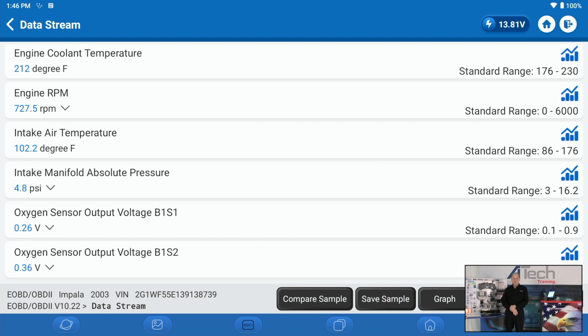Now, let's look at, if I pull this back up, we've got our O2 sensors. And the O2 sensor right now is switching, the one right above the bottom. The one at the bottom should be fixed most of the time when you're looking at it. If it's not fixed, you have an issue. So we're just basically looking at data.